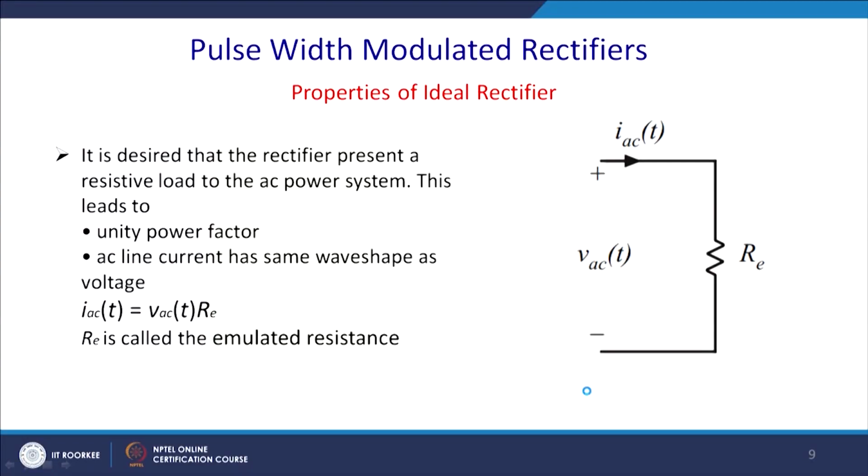So, now let us conclude the effect of the source inductance on all types of converter as well as the rectifier. Due to the effect of this source inductance, THD generally improves, but you get lower DC voltage and lower power factor.